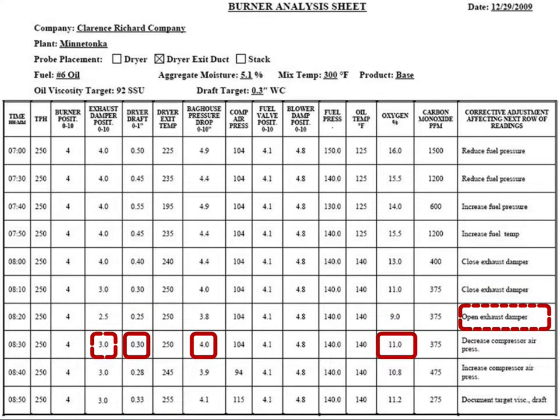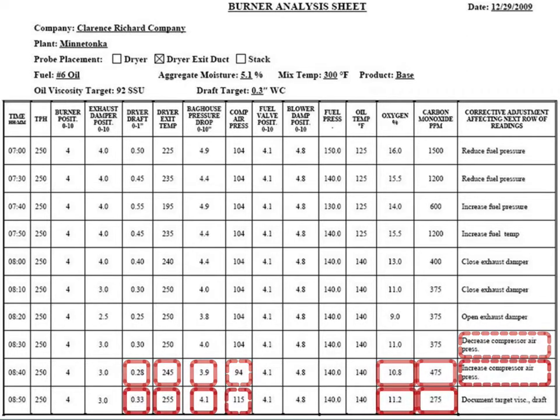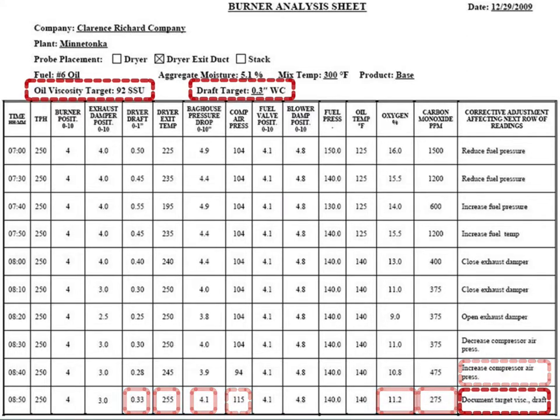The oil temperature should be adjusted during the tune-up. The oil should be measured for viscosity immediately after the burner is tuned. Document this viscosity measurement and continue to check viscosity from load to load. If the fuel is consistent, the temperature won't need to be changed from load to load, and measuring each load